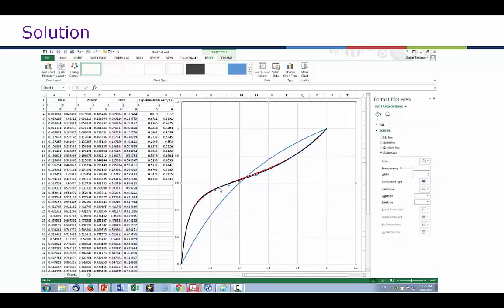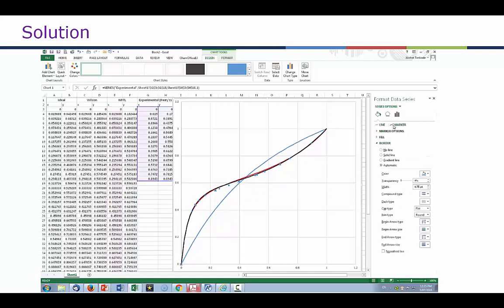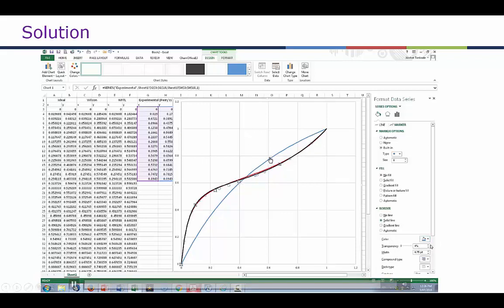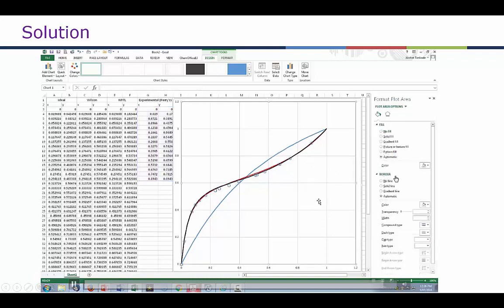So as we can see, the Wilson and NRTL come close to predicting the experimental data. However, the ideal gas equation of state is far off the prediction. In this case, it looks like Wilson gives us a slightly better prediction. There's only a small difference in the region around 0.5 mole fraction for ethanol.